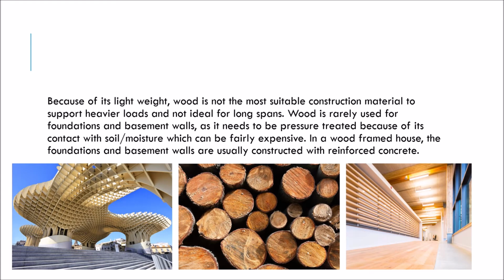Because of its light weight, wood is not the most suitable construction material to support heavier loads and not ideal for long spans. Wood is rarely used for foundation and basement walls as it needs to be pressure treated because of its contact with soil or moisture, which can be fairly expensive. In a wood frame house, the foundation and basement walls are usually constructed with reinforced concrete.